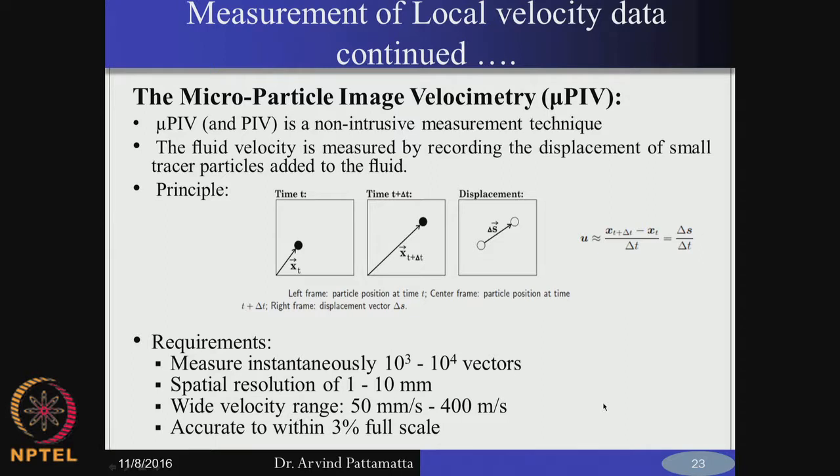Every few nanoseconds or microseconds, depending on the time scale, you pulse it, and the particles will respond by glowing. This glow will give you the track of the particles. So, you keep recording images with a CCD camera at different time intervals, every few microseconds or nanoseconds, and then look at the snapshots in time.